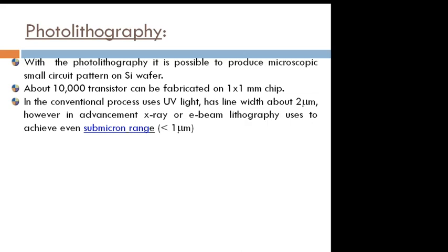If I have 2 micrometers, and it is allowed to pass through a very small mask made of glass, there is a possibility of diffraction, and hence lateral spreading in the IC fabrication, which is not allowed. So this is one of the minuses of this fabrication.